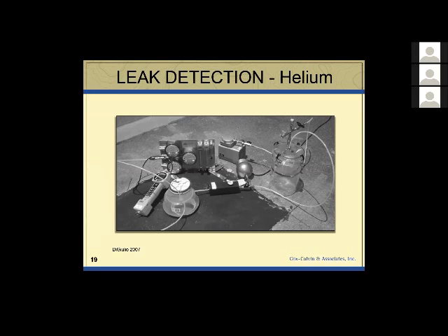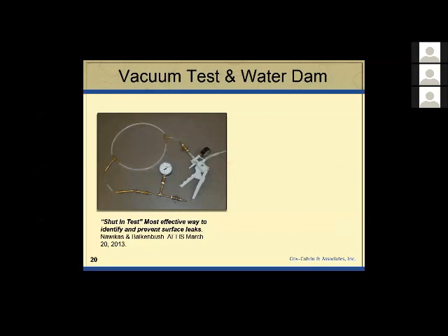Some people use VOCs like isopropyl, and if you have helium or isopropyl in your sample, he's getting real-time readings with the device there on the left side, then you realize you have to fix it, you tighten up, et cetera, till you have no leaks. You can do that, but you're not going to do very many of them in a day. It's obviously cumbersome, it's costly, it's difficult to carry, you can't carry the helium on an airplane, et cetera.